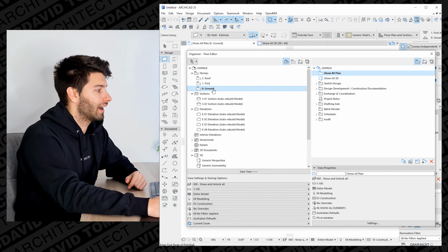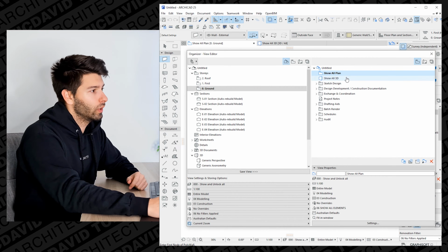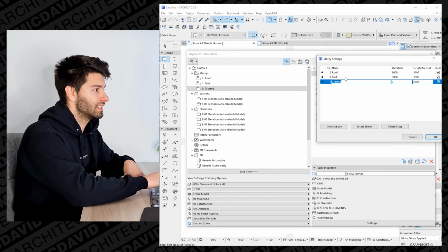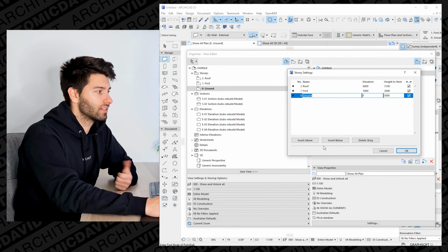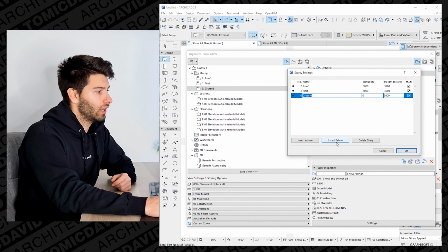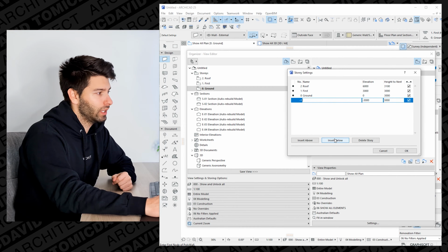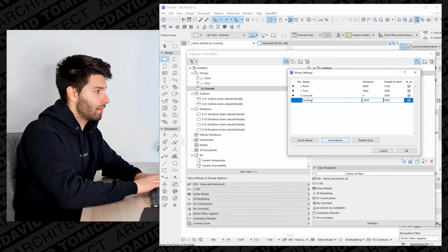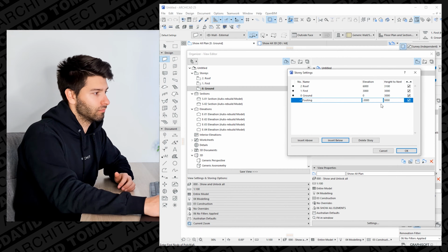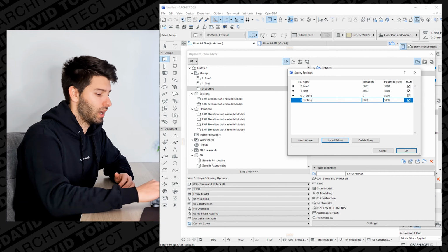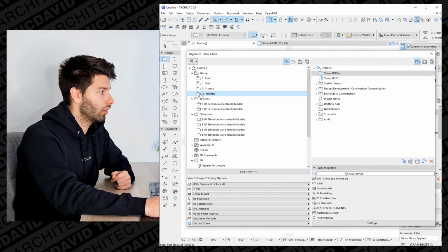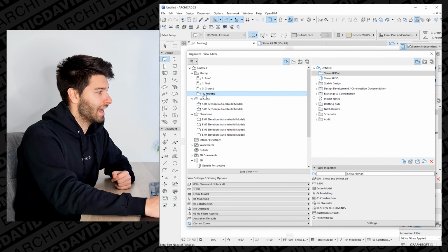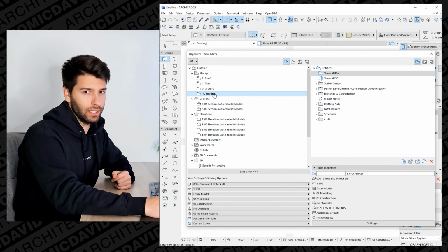If you wanted to create another layer, another level, we would simply press Command 7 or Control 7, depending on what system you are, and adjust the story settings. So as a very basic example, if we go insert below, type footings, and just for the purposes of argument, go minus 172. This is in millimeters in Australia. Clicking OK, you'll see that story automatically pops up here.